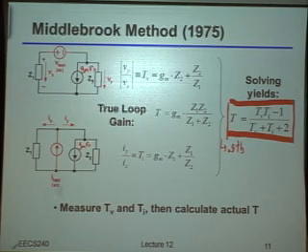By the way, just as another thing to mention, hopefully briefly so you guys know about it, in SPICE in particular, there's an option you can set that basically says .option accurate, which automatically retunes a lot of the simulation parameters to try and improve the accuracy of the simulation. So a lot of times, for things that you really care about, you'll just go and add this .option accurate in, just so that by default you'll get a better estimate of things. Now, why is it that you don't necessarily always want to have this option on? Yeah, it just can take longer to actually do the simulation, right? And for stuff that maybe doesn't really matter, the default accuracy is good enough, it'll run a lot faster if you don't do this, okay?